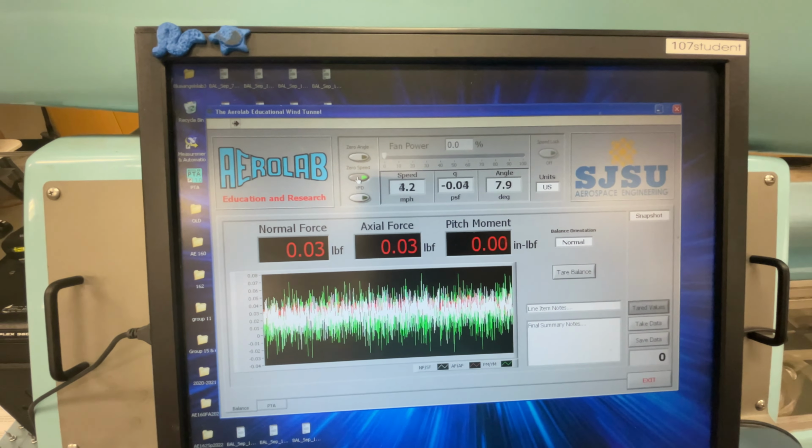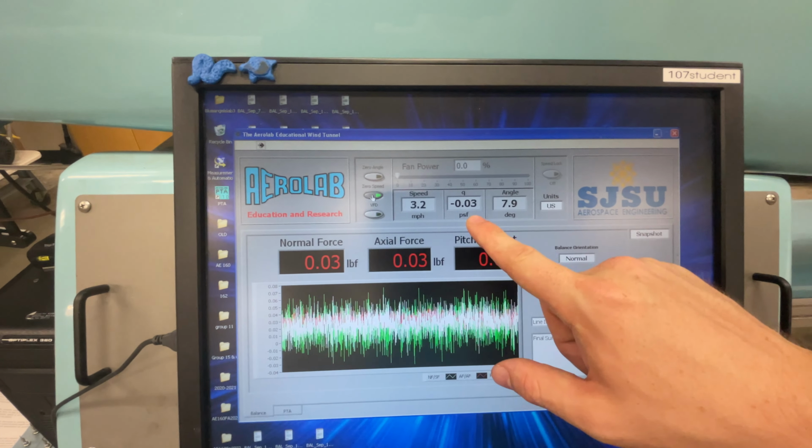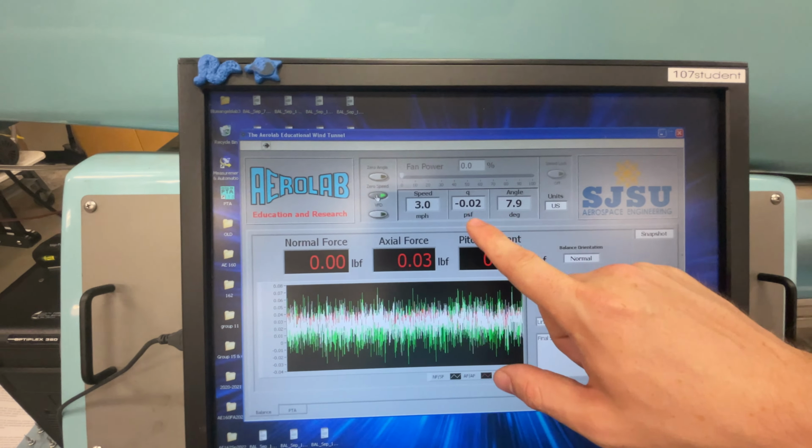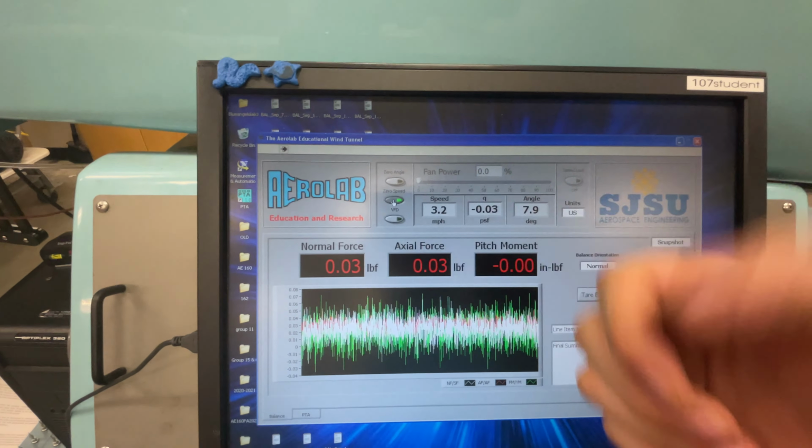So what you might want to do is update that calculation a little bit. You can use your own density. Use this value for Q, like it says, but use a correct value for density to calculate your own velocity. And if we wanted to do that, we could use the ideal gas law. Pressure equals density times specific gas constant times temperature. So if you know the gas, you know the temperature, and you know the pressure, you can calculate your own density.